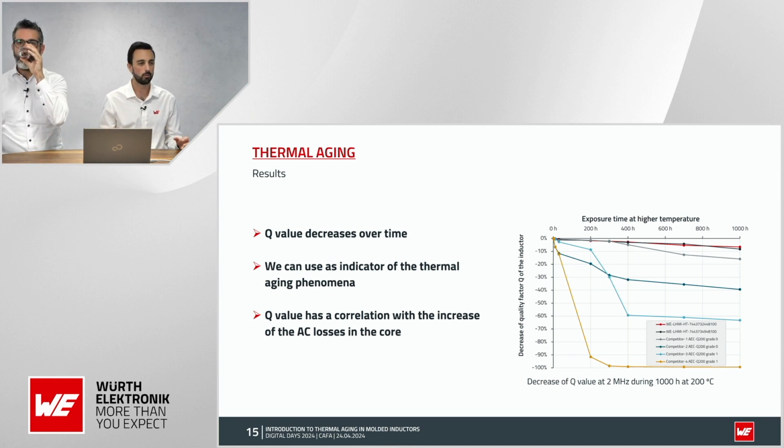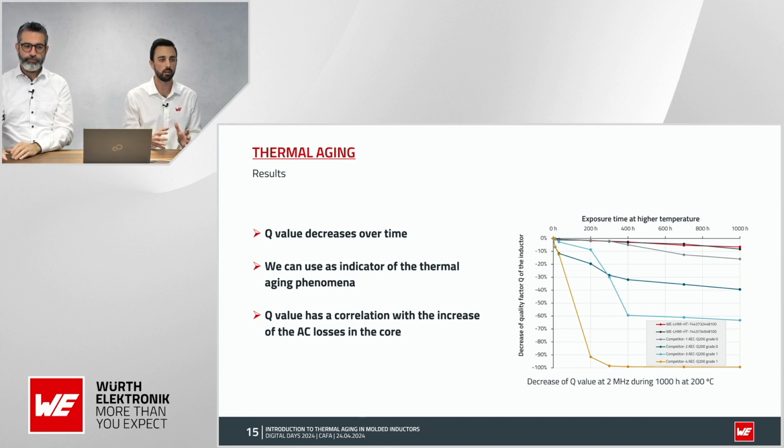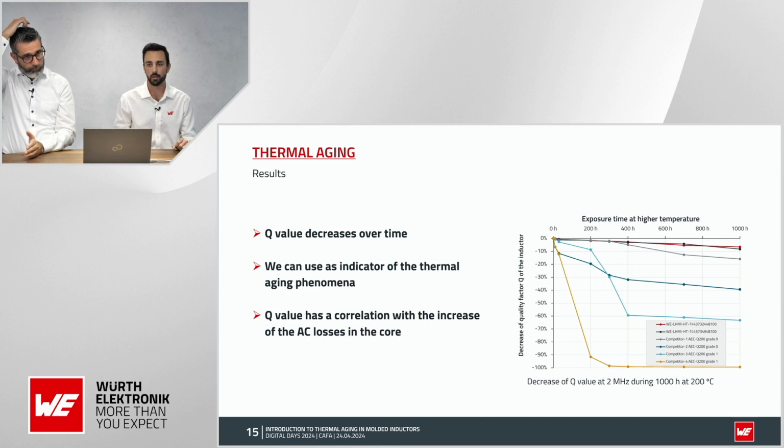First of all, if we are testing parts that are qualified for 150 or 125 degrees, why are we exposing them to such a high temperature? It's because the parts are so robust that if we test at a normal operating temperature of 150 degrees, this test will take a very, very long time.